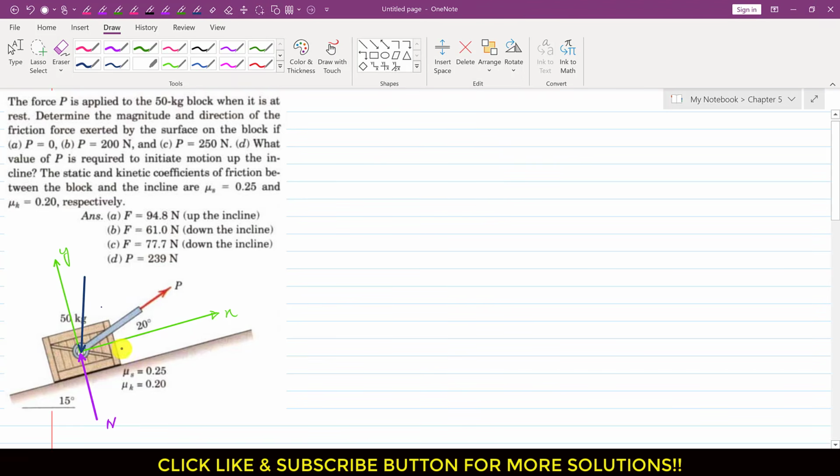And similarly, let's assume that the friction force is acting along the plane in the downward direction. So let's say that this is our friction force that is acting between the two surfaces. This is the friction force. This is the weight, and weight is 50 times 9.81, so this is 490.5 newtons. And we can resolve this P force into its components along the x and y axes.